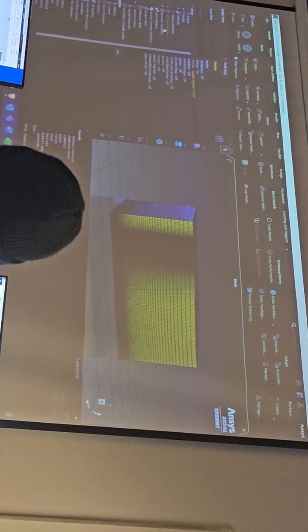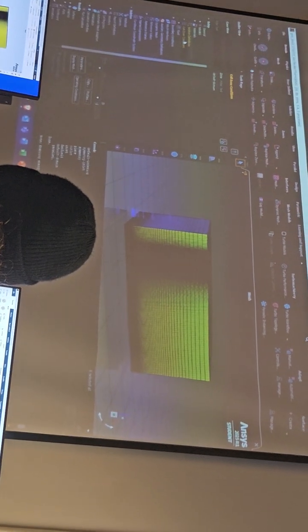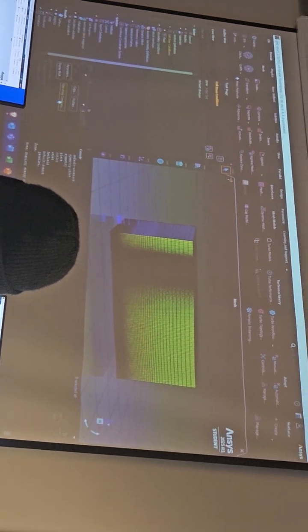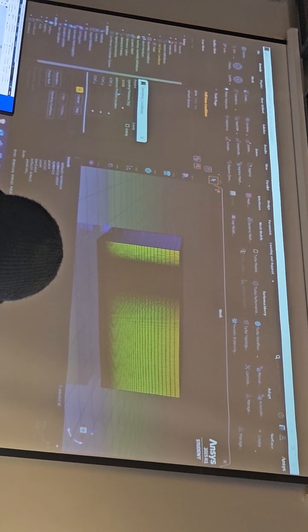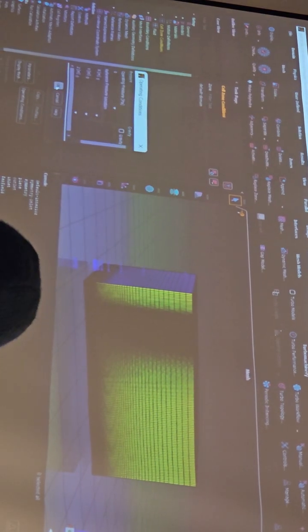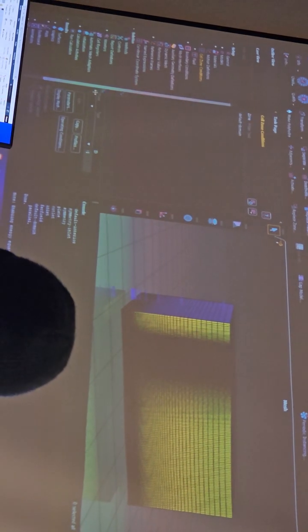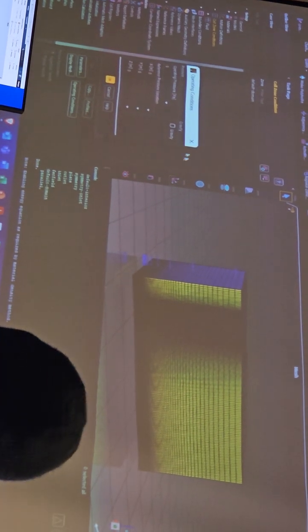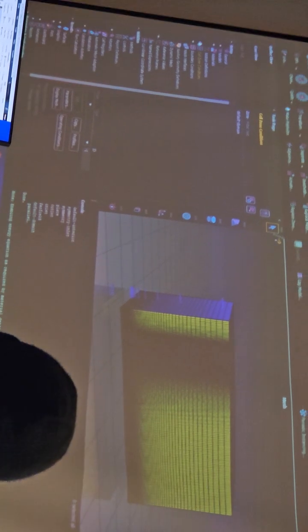Okay, then the next thing I'm going to do is to set the cell zone conditions. I double click that, and I'm changing the operating conditions at the bottom. There is this operating pressure, so I set this to 0, so that the absolute pressure is equal to the gauge pressure. So in cell zone conditions, operating pressure to 0. That's it in cell zone conditions.